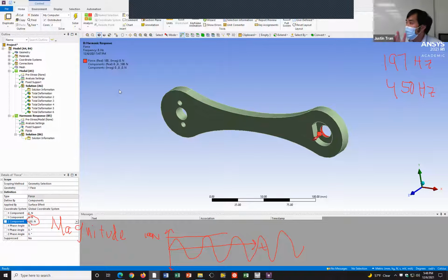And so are there any questions on this so far? Yeah. Why did you pick 100? Yeah, that's a good question. So I picked 100 here mostly as just a dummy number. And so most of the time you would actually pick what the magnitude of your vibration forcing is going to be. And so, I know a lot of you are interested in doing an analysis of an earthquake on the building for the final project. And so, you would actually put the force amplitude of what the earthquake is here for that. But I just put 100 here just to make it simple.